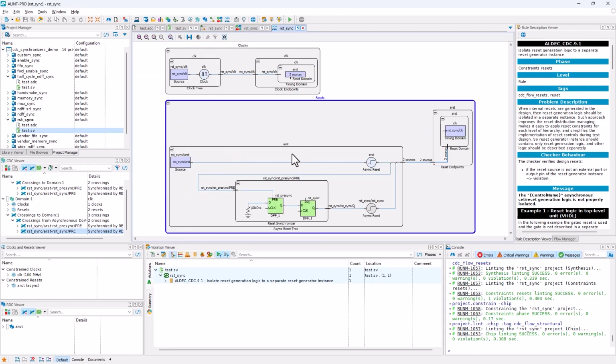And so now that we've expanded them, we can see in full detail what it is that I wanted to show. In particular, we see the reset synchronizer source here, feeding into two different places. First, this is an asynchronous reset, and it's being fed and used as a reset in a design. But it's also being sampled and used to generate our synchronous reset. And it's generated via this reset synchronizer, which is shown here. And so this reset synchronizer, recognized by the tool, generates our synchronous reset, which here it's still listed as asynchronous reset, and that's just because, well, it still is asynchronous.